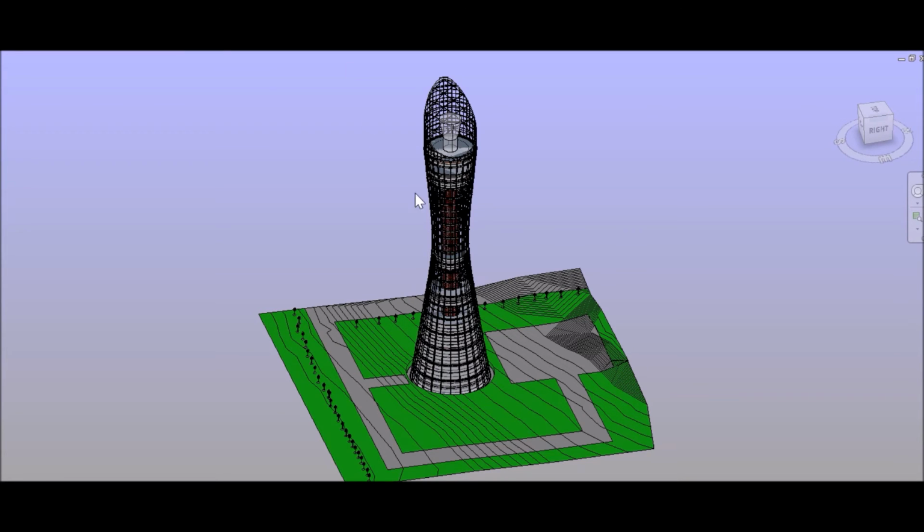Then I followed it up with the massing of the whole structure. I added floors and roofs at different levels, and I recreated all the 36 floors in the model. I also added some topo surface elements. I used my own user-defined material, which is actually called my grass. I was also able to place some environmental elements, and I was able to give the structure a building pad, which showed the structural foundation.